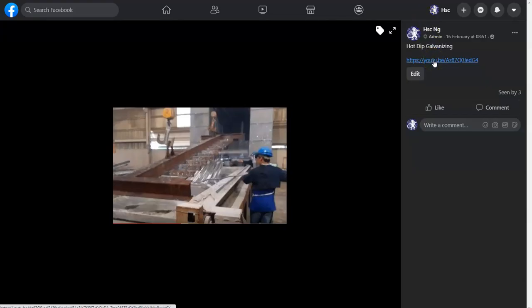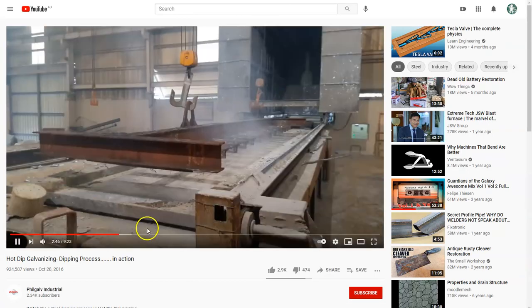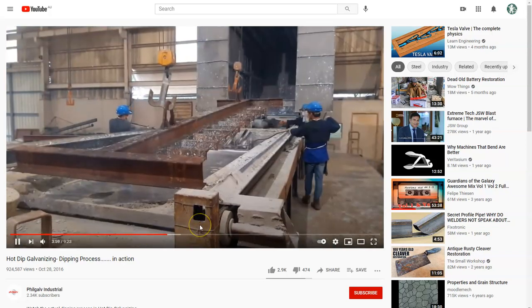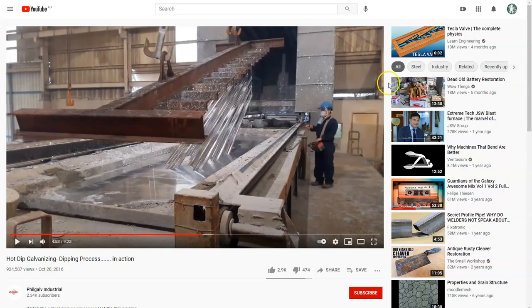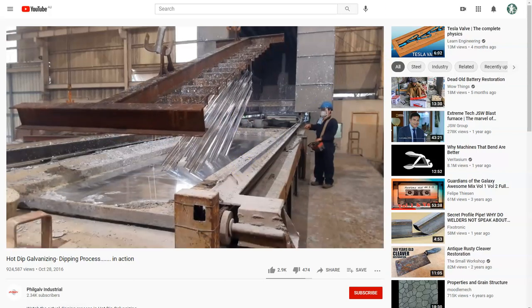Here we have hot dip galvanizing, which is another coating. This is where we use a process where we are using liquid zinc, and we dip the steel in liquid zinc. We also use products like zinc alum these days, which is zinc and aluminium. That's a very commonly used product for sheet metal. And if it's coated in a layer of plastic, it's then called color bond, which provides even another layer of protection on top of that. Anyway, so you can see the material being hot dipped.